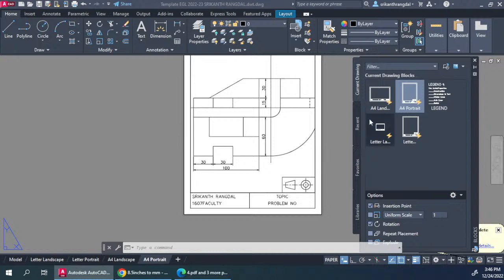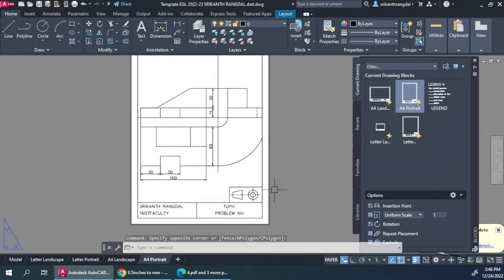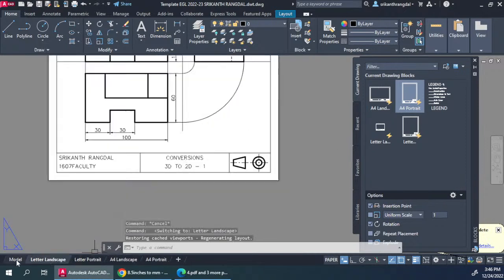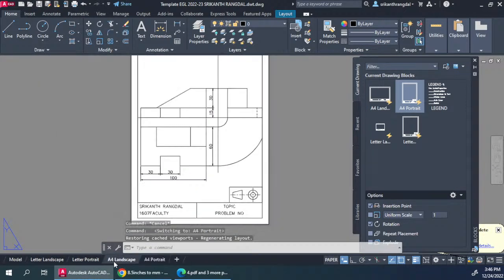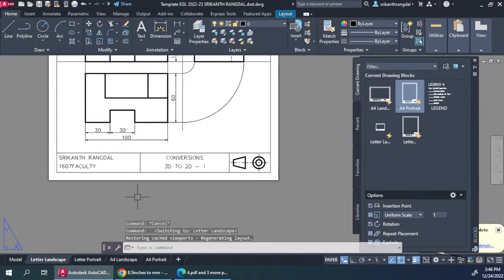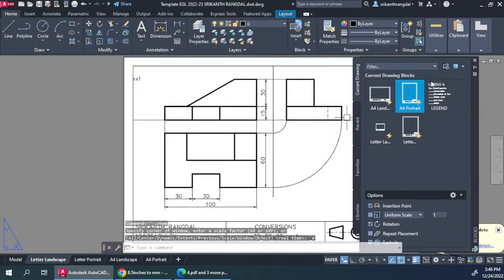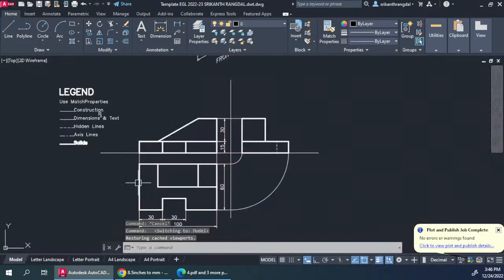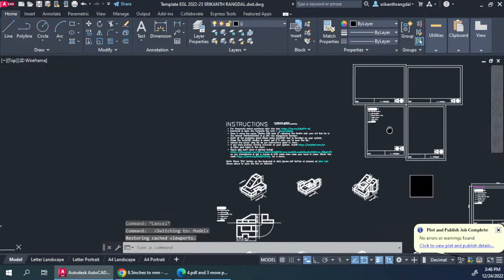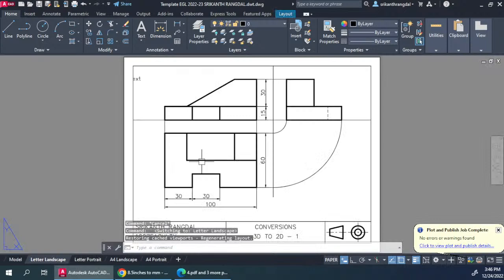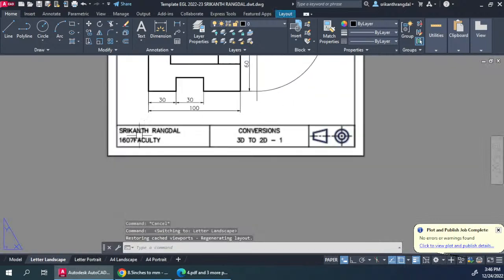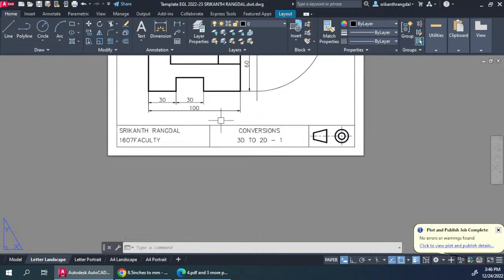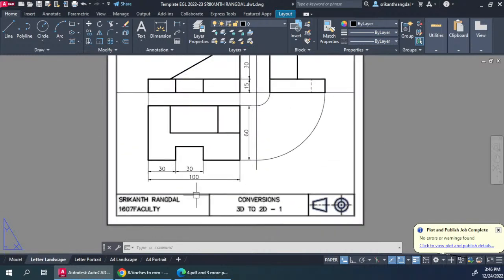Okay, thank you. And yeah, I guess in this session we just found this thing out. Let me just quickly go through what things we learned in this session. So first thing we learned is that there's no need to create a boundary in the model space. We can keep the boundaries, and all the topic related stuff, table related stuff, all can be pushed over to the layout space.